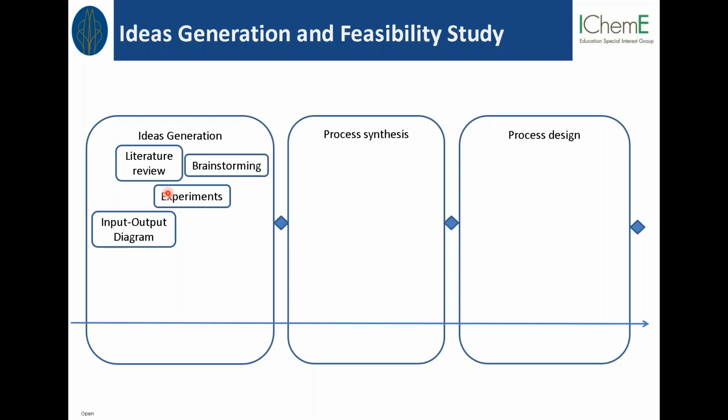And then when we do the input and output diagram, we know that this chemical A makes chemical B. Is there any byproduct? Are there any other utilities that we're going to need, for example, if we know it? And from that, we then try to put some numbers. I would like to call this the input-output mass balance. So we have incoming, we have outgoing, the product that we're going to have, and then based on the information that we have, like yield, selectivity, conversions, or whatnot, we can make a rough mass balance from this input and output diagram.